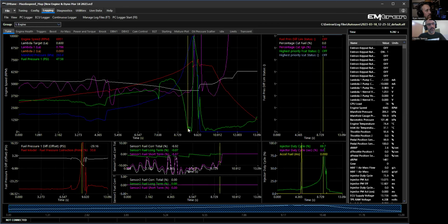And then if you look at boost pressure, we're already at 263 kPa absolute, so it's about 163 gauge. We lost about almost 20 plus psi of boost or pressure. 33 psi, if you look at the bottom left, way down, right here.